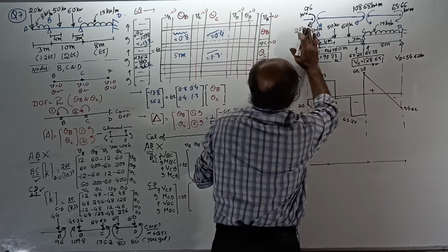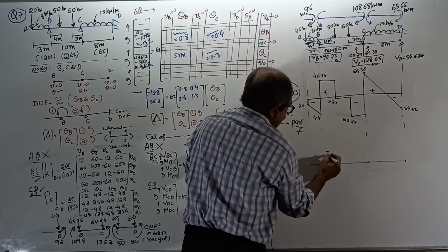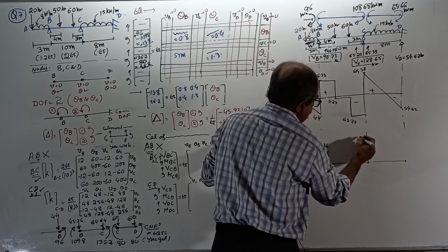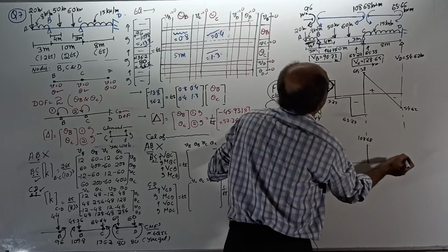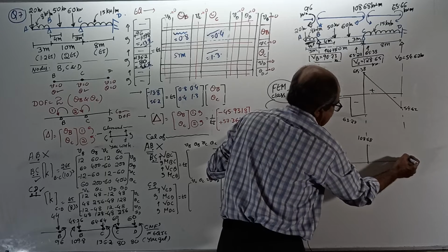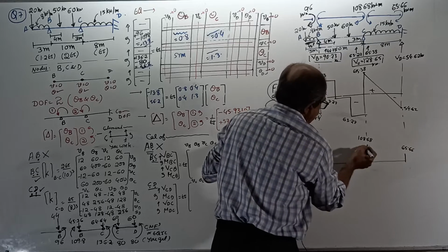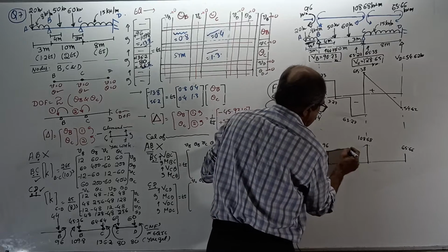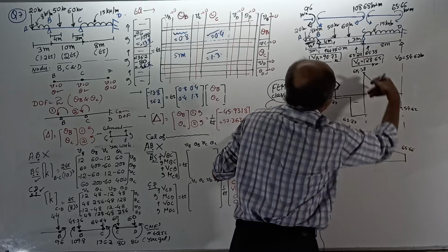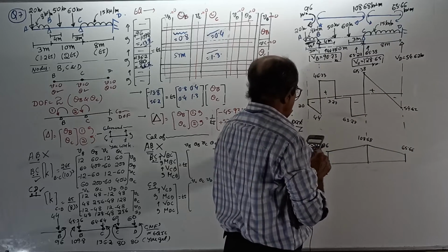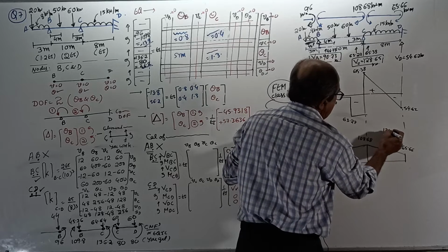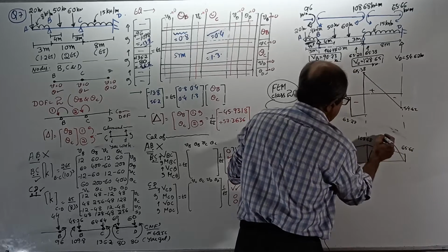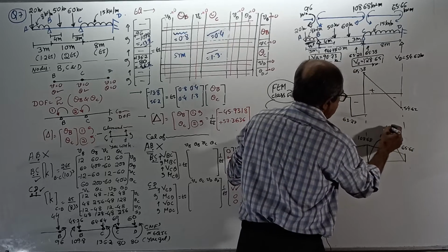See, no superimposing here. 96 here. Here, 108.68, a little more. 108.68. Here, 65.66. Irrespective of whatever is loading, joined by a straight line. Superimpose bending moment diagram due to simple support beam. 120 here. How 120? Okay. Parabola this way. 120. See, this is 120. How it came? WL square by 8.